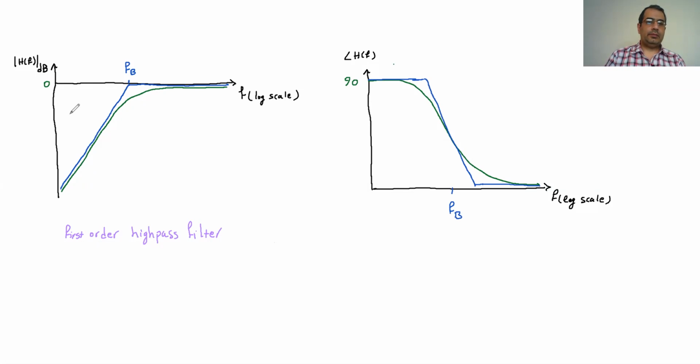So you plot the magnitude of the transfer function of the filter on the vertical axis in decibel, and then the horizontal axis as a logarithm. Another way of plotting, which is not the Bode plot, also just uses logarithms. Instead of using decibel, just use the normal magnitude, but use the logarithm scale for the magnitude and the frequency for both of them, and plot them in a log-log plot.